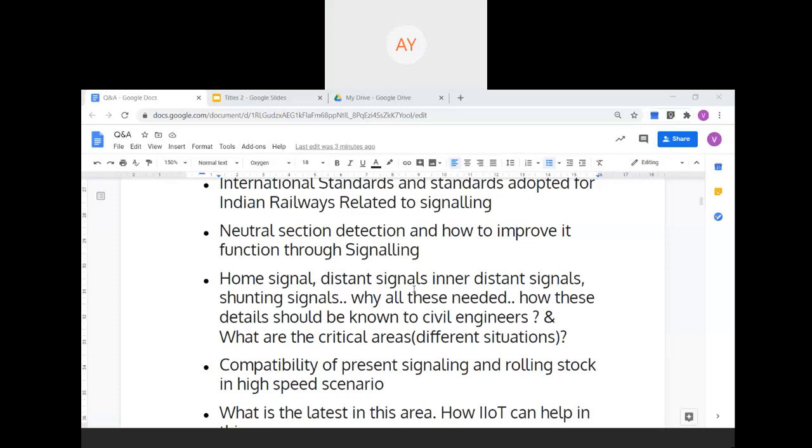Immediately after the neutral section, there is another magnet which tells it now you're beyond that, so the system connects it automatically. There's nothing to do with signaling here. This is a separate control device for switching those circuit breakers, activated by these track magnets placed along the track near the neutral section.